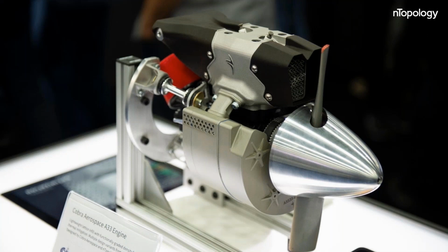They're actually like, hey, we're going to pick a part that makes sense for advanced manufacturing, which is this engine block, right? The engine block was a cast part previously, and as an engine block, which you can kind of see through here in the center, when it was cast, it had to be solid. Because it's 3D printed, you don't actually need to make it solid. And actually, the pressure in the cylinder is not so much that you need a giant brick of aluminum.